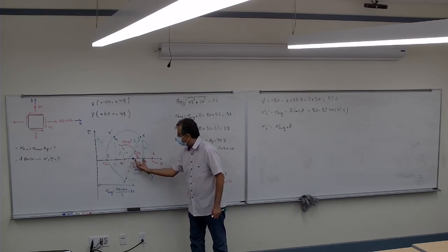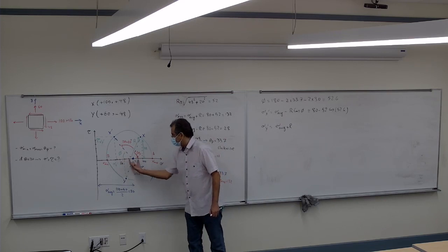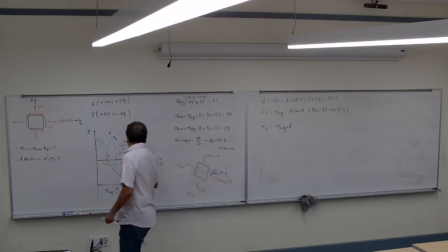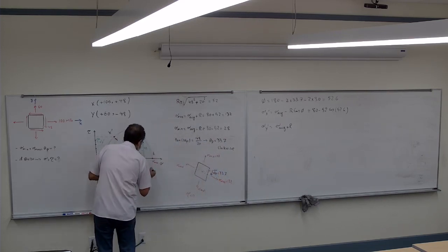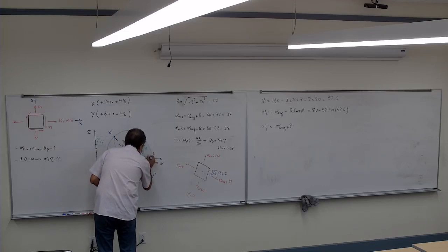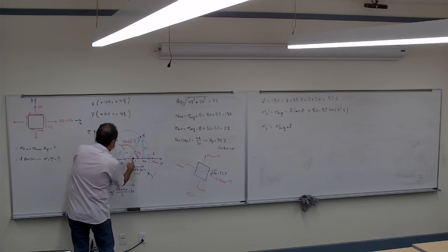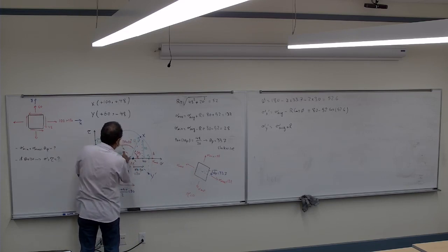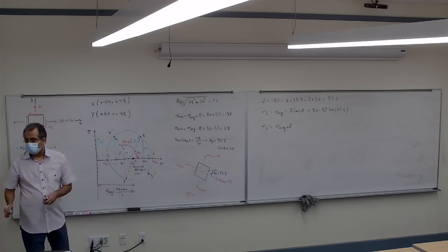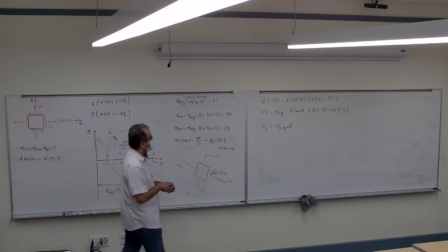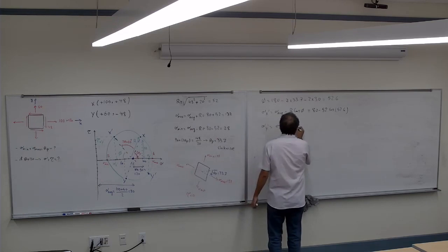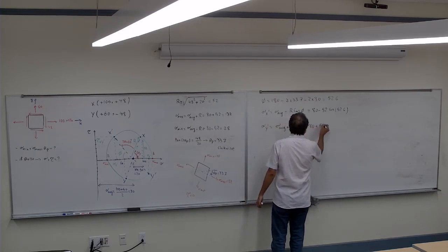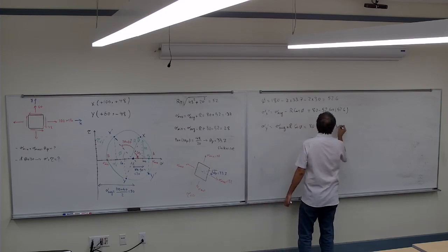The sigma Y prime is the sigma average plus, now look at it, the sigma average plus this. What's this length again? It's the same as the length there. So this length and this length are the same, so this angle is the same. So it's the R cosine phi. This is the R cosine phi. So it's going to be 80 plus 52 cosine 52.6.